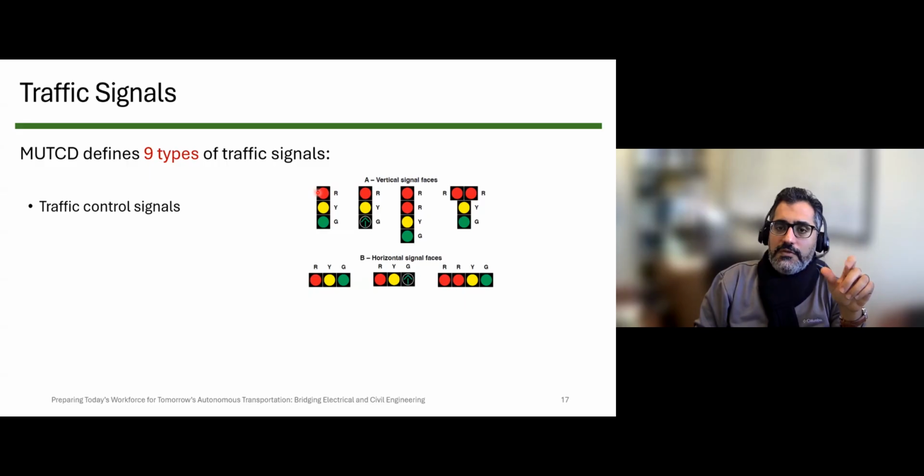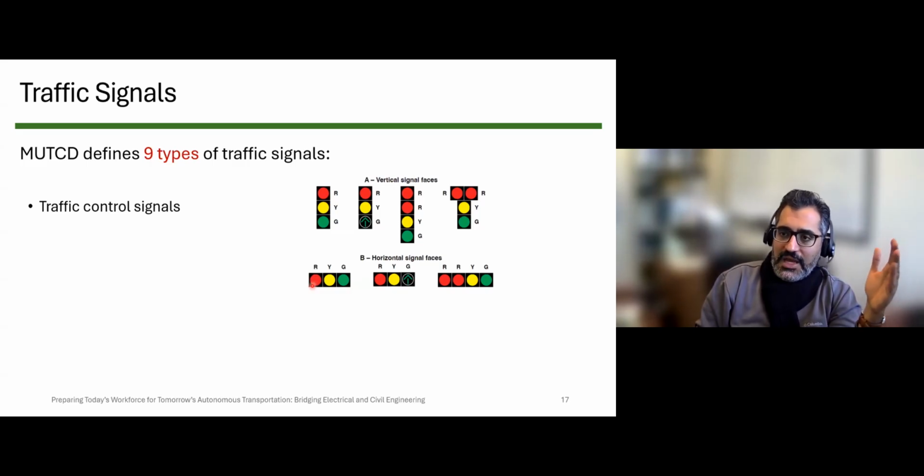Now, if you rotate the traffic signal, it mostly happens because of the vertical clearance. If there is not enough vertical clearance, so you cannot place the traffic light vertically, you should place it horizontally. Usually, red must go on the left side, because math and English writing start from the left. So the important message should go on the left.